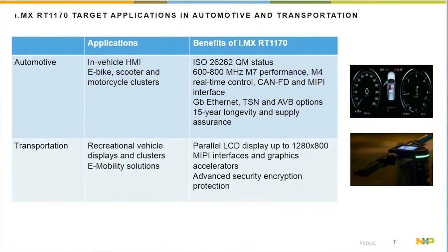Some of the attributes I wanted to point out: what's unique about the RT1170 in comparison with the other i.MX RT products that came before it is that it is automotive qualified. This device did go through the AEC Q100 testing. It is ISO 26262 qualified to the quality managed process. So you have that intrinsic safety and security attribute that's typical in all automotive quality and applications.